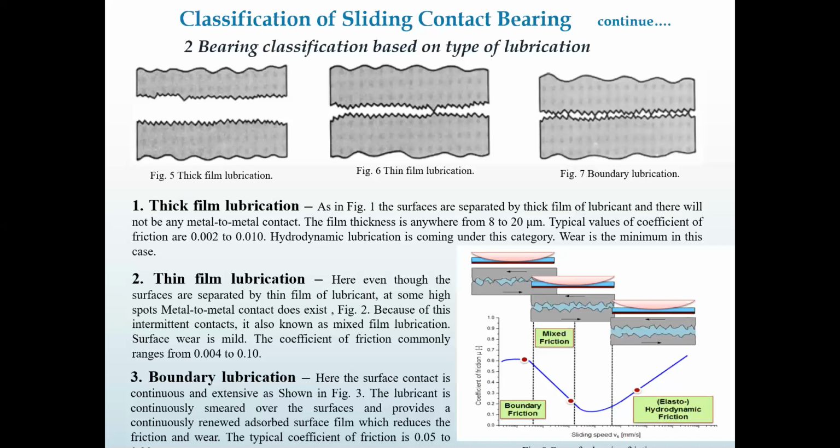Because of that, localized patches of the fluid film cover the surface, and a few crests are in contact, while most of the part is not in contact between the two surfaces, shaft and journal.